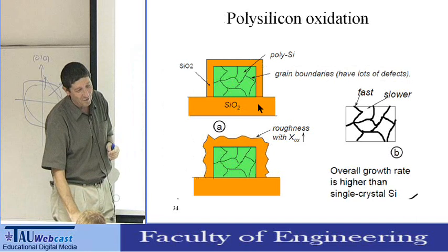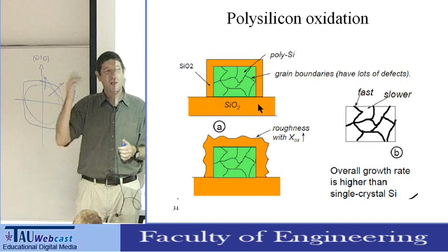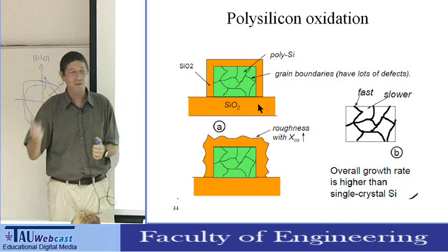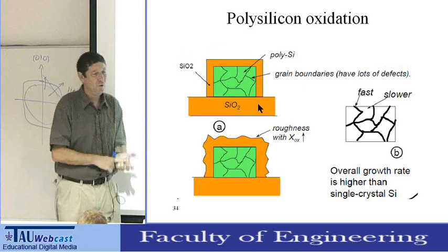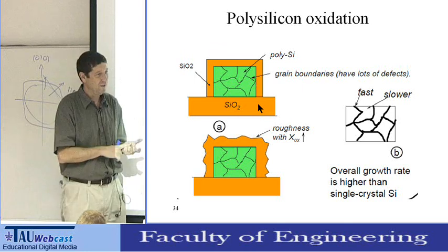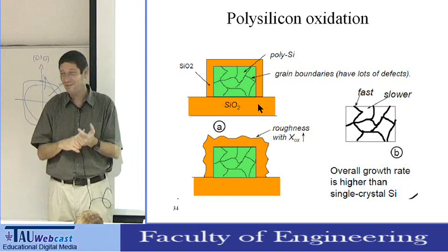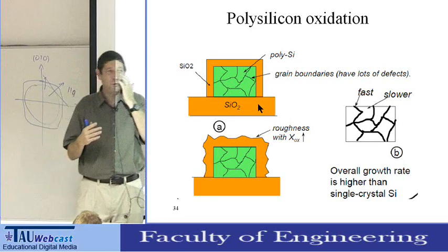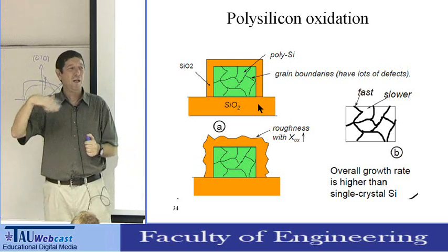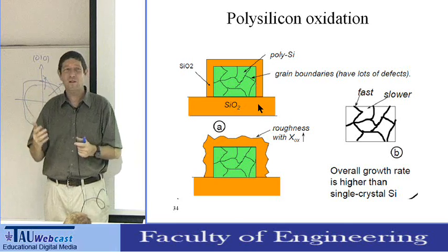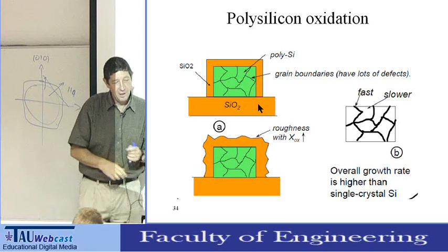Now, if you really want to model it, it's complicated because all the coefficients that I described to you before, Ks and the diffusion coefficient, are all functions of the stress. And the stress depends on the growth rate. And the growth rate depends on this function. So you understand that I described to you only the simple model, not taking into consideration secondary effects, which are very significant for nanostructures or very small structures.